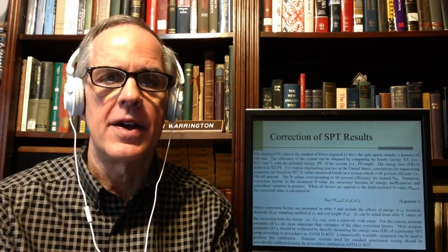The rod length can be important because when you start getting a long rod, you start getting wave effects in the rod, and the whole thing acts differently than it does for a shorter rod. And so that's important. Those three are fairly easier to correct for. The one that drives everything is the energy ratio, the CE factor.